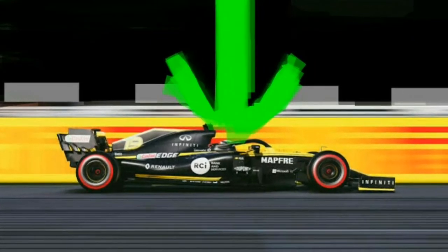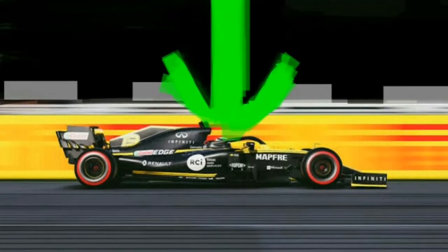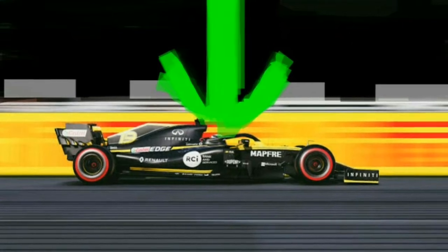Most of us consider downforce a better thing, but I have to say downforce is an evil. It has a bad side and a good side. So let's discuss. It is because downforce is the byproduct of aerodynamic drag. If we have higher downforce, there will be higher drag, which will resist the motion of the vehicle. So a car with higher downforce definitely has more air resistance.